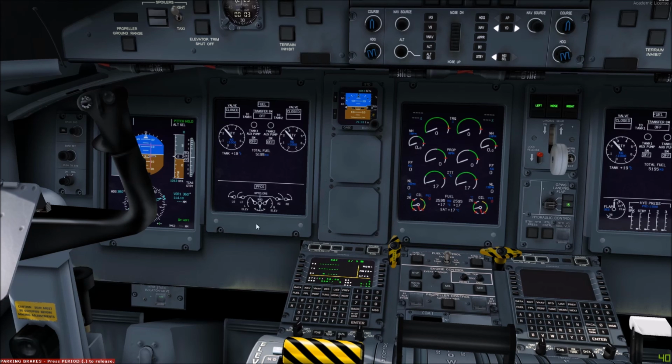The fuel display itself shows the quantity in each tank, shown in the form of a round gauge. We have the status of the fuel valves themselves, currently closed as the engines are offline, and the status of the transfer between tank 1 and tank 2, and again that's switched off as you'd expect. The total fuel capacity is shown as a digital readout as well as the analog gauges, and the fuel readout for each tank is shown again on the engine display.